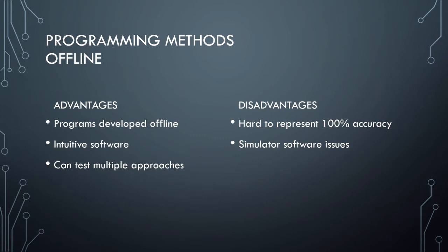So with a teach pendant, you can see everything in that physical space and you know the exact relation, whereas in software, it can be a little bit of a guess. You might have to move things around a little bit to adjust. So oftentimes we can get close with software for robotic programming, but sometimes we may have to tweak it a little bit, bring the arm down a little further, out a little further to really get it where we want it.